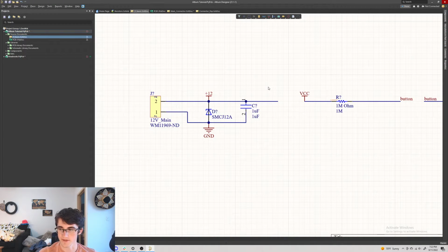And so you need to know which resistor is what, because similar to having multiple resistors, they're probably not all going to be the same value. You might have some that are 10K, some that are 100K, some are 1 mega ohm. They might be different sizes. So it gets very convoluted, one, when you're ordering the board and getting parts for it, but also when you're trying to solder the board and debug it. So we use part designators. You'll see a trend where resistors start with R, capacitors C, diodes D. A lot of microcontrollers and logic gates start with like U. A lot of transistors start with Q. But you know, you'll kind of see that here, but your job is to give it a number.